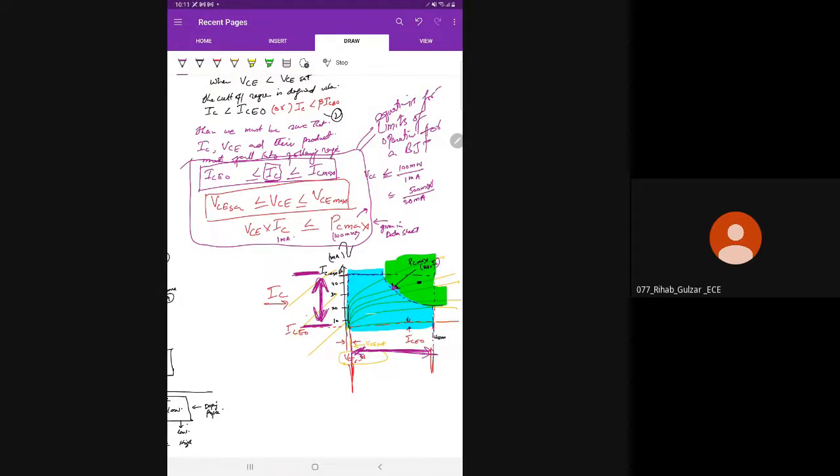तो इस चीज को पहले समझने के लिए you always have to consider its data sheet, then you have to identify what are the voltage and current levels that can be applied. In other words, I can summarize it in this way कि हर कोई ट्रांजिस्टर हर किसी सिग्नल के लिए सुटेबल नहीं होता है। अगर आपको एक सिग्नल एम्पलीफाई करनी है, BJT acts as an amplifier also, अगर आपको कोई भी सिग्नल एम्पलीफाई करनी है, आपको देखना है कि उसकी वोल्टेज लेवल कितनी है। Suppose you are trying to amplify the human स्किन से, जो ह्यूमन स्कार्प से जो सिग्नल्स आती हैं, अल्फा बीटा, या ब्रेन से अल्फा बीटा एंड गामा वेव्स, या कार्डियक वेव्स जो आती हैं, या इवन EEG